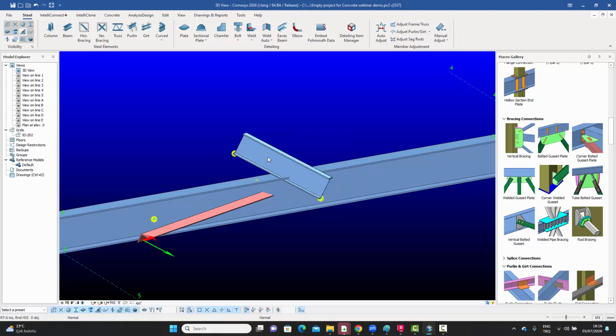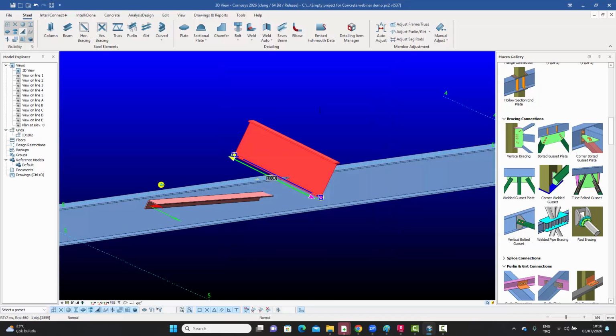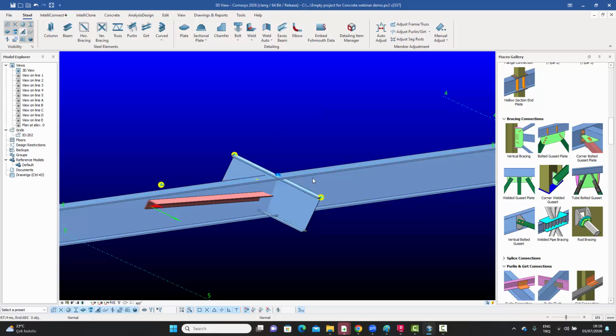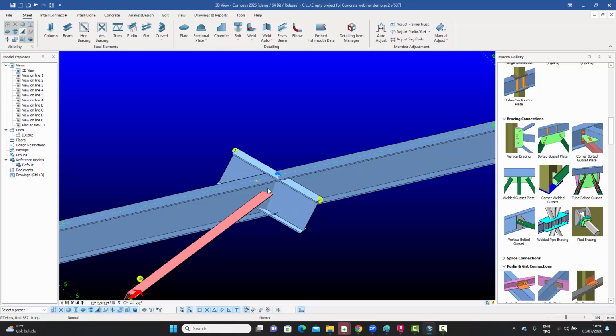Now, it might not be in the perfect position, it might not be the perfect profile which you want, so you can just change the profile like that and press Control W to bring it in front of it. But this is now oriented according to that. So this little thing which we've added in the direct entry method is very useful. You just hover over the point and you say LY or LX or LZ, any one of those. You can create a temporary member left and right of it, which you can then use to make the macro work for you. So let's do that.